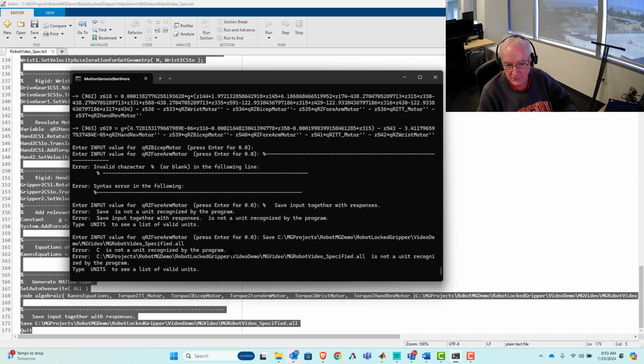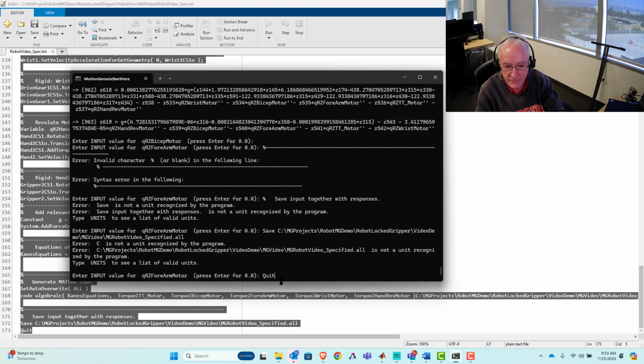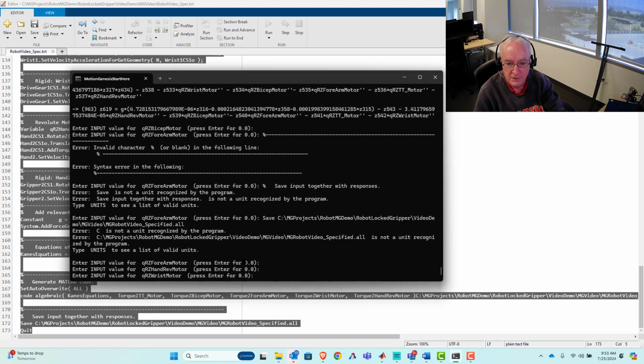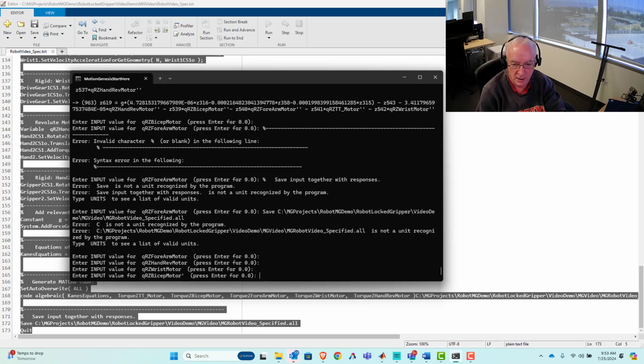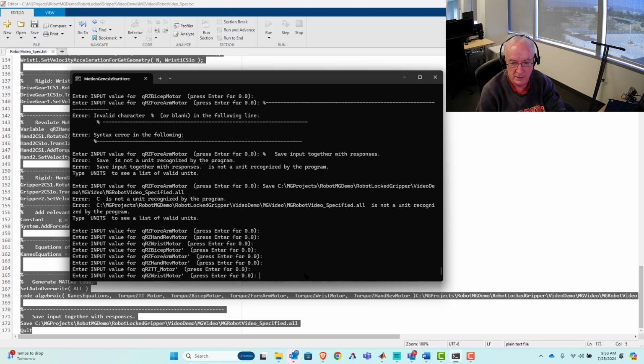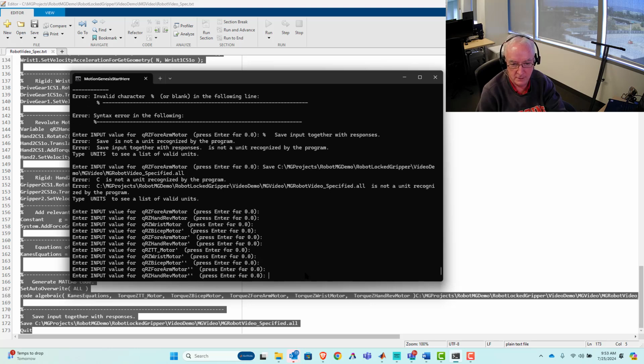It's essentially saying I do not have initial conditions for all these motors, so let's not quit. Just keep on allowing the default assignment of 0, which really is the assignment for the angles as defined for a vertically positioned robot. So we'll just go in here and enter these.